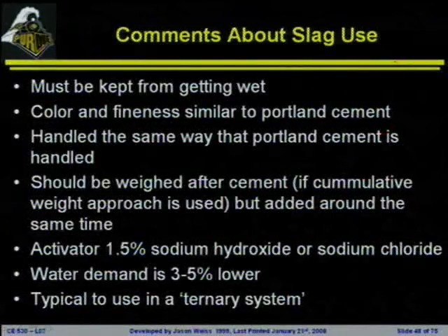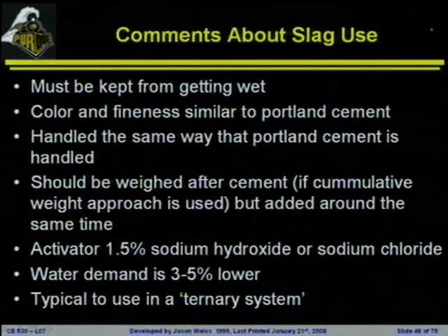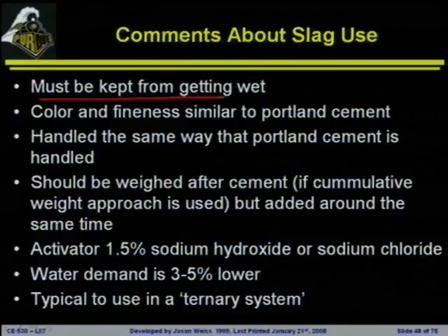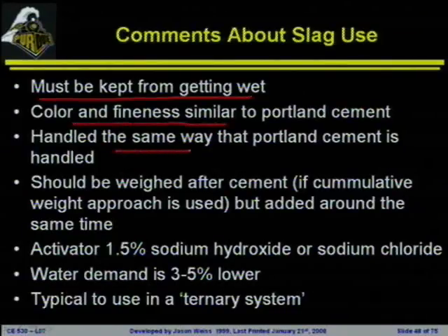Slag, much like Portland cement, is going to undergo a hydraulic reaction, which means when it comes in contact with water, it's going to react. So you want to keep your slag from getting wet. Just like Portland cement, you wouldn't leave it sitting out in the rain. You can't do the same thing with slag. Color and fineness are going to be very similar to Portland cement. It's handled very much the same way Portland cement is.